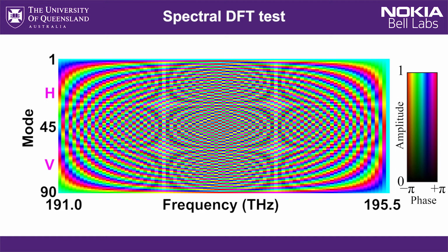This is that goal. For our first test, we'll be working with frequency bands approximately 50 gigahertz wide, which means there's 90 across the 4.5 terahertz of the device. This coincidentally means we've got the same number of spatial and polarization modes as we do spectral bands for this particular 50 gigahertz example. But as we start going to narrower spectral slices, we'll start to repeat the matrix columns several times.